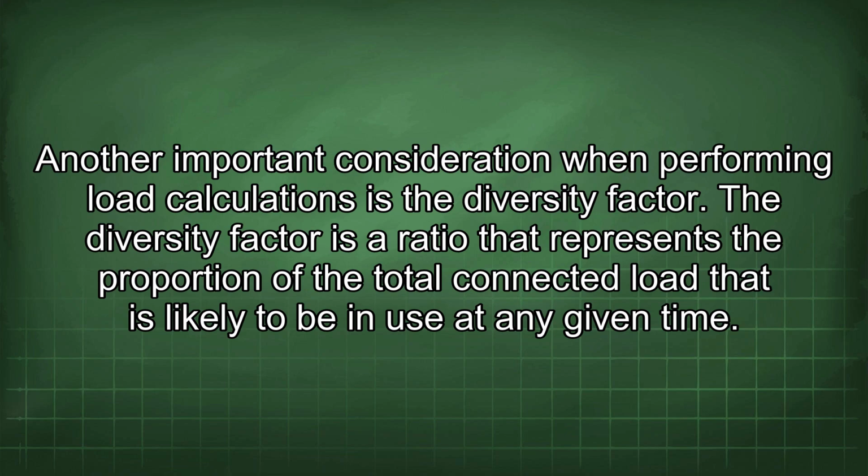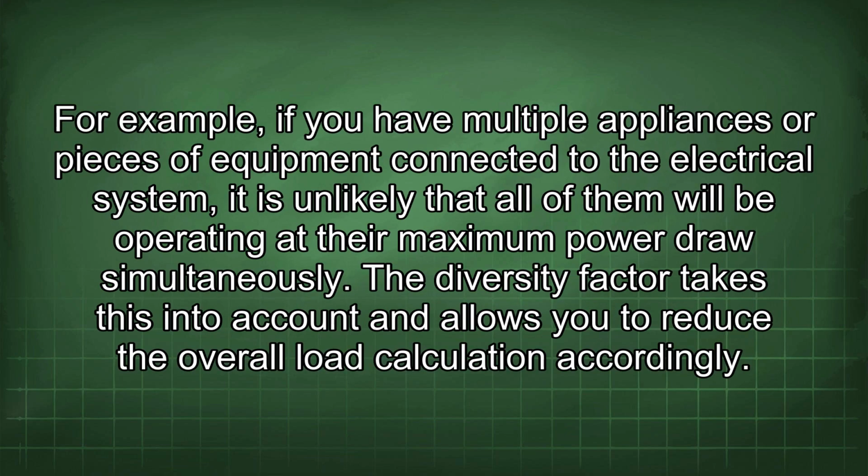The diversity factor is a ratio that represents the proportion of the total connected load that is likely to be in use at any given time. For example, if you have multiple appliances or pieces of equipment connected to the electrical system, it is unlikely that all of them will be operating at the maximum power draw simultaneously. The diversity factor takes this into account and allows you to reduce the overall load calculation accordingly.